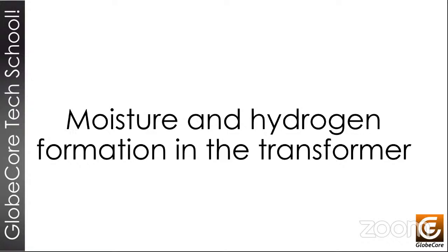Hydrogen, on the other hand, is one of the gases that are constantly formed and generated when electrical or thermal faults occur inside the transformer. And the correct measurement and management of these parameters is rather critical if we wish to extend the service life of our transformer units. Next slide, please.